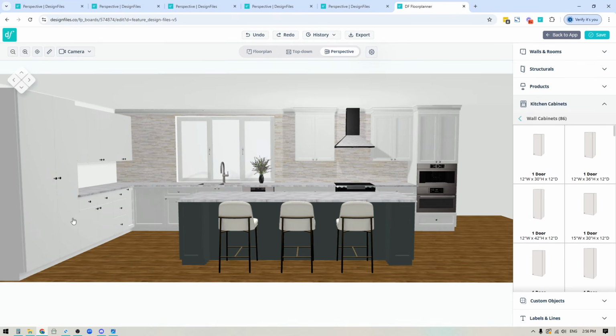And then once you have all your cabinets in place, remember you do have filler cabinets for each of your wall, your base, and your tall cabinets. So it'll allow you to fill those gaps where you need to. If you are going to be doing a double stack for your wall cabinets, just know that you'll have to adjust the distance so the other ones will sit directly on top of your original wall cabinets.